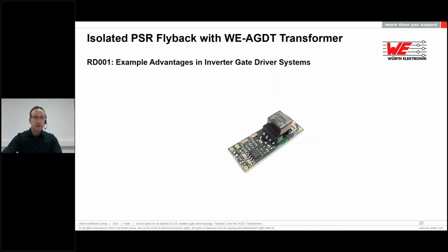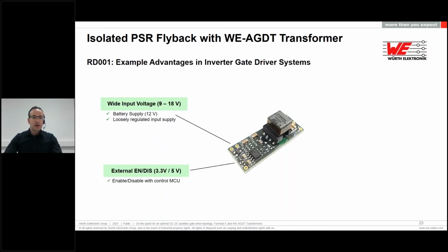Let's see now some of the potential benefits of using the reference design in an inverter application, for example. First, the wide input voltage range allows powering the circuit directly from a variable or loosely regulated input supply, like it might be, for example, a 12 volts battery. The design also provides the possibility to enable or disable the auxiliary supply externally via a microcontroller.